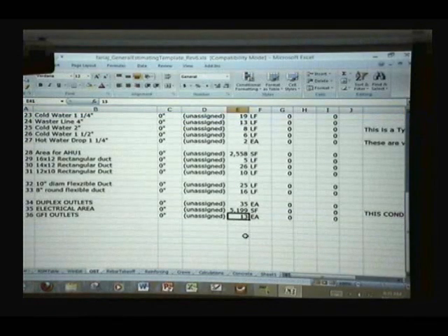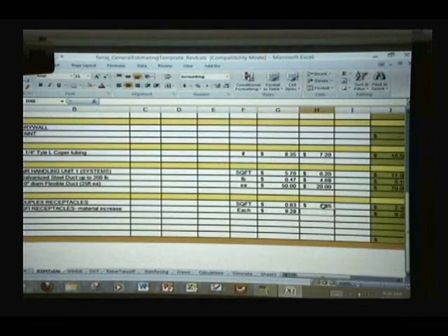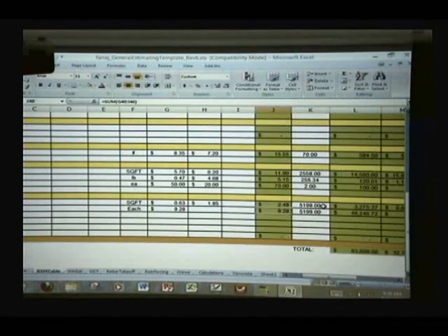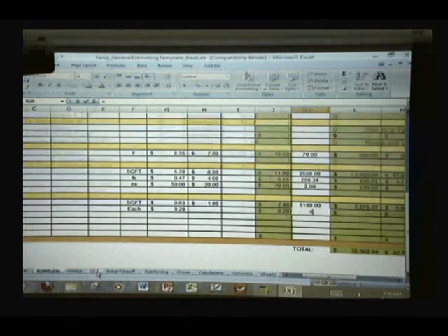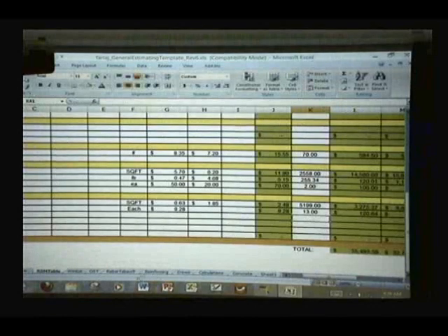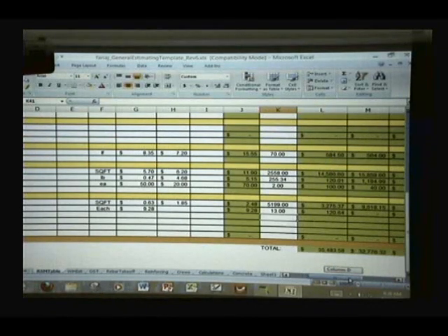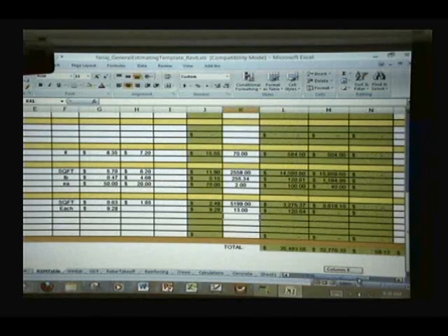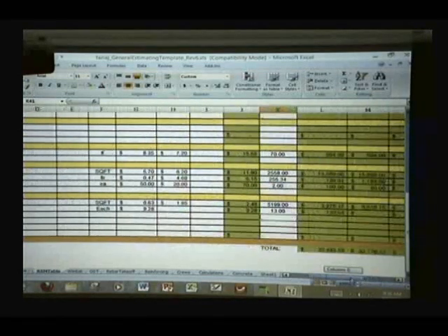13. Exactly. So now you have to go to your RS Means table and in the quantity of work. That's not the quantity of work. This? No, that's the cost for materials. That one, exactly. That one over there. That's equal to 13. So that's a lot more reasonable. You're paying $120 more for your GFIs. That's a lot more reasonable than $13,000, don't you think?